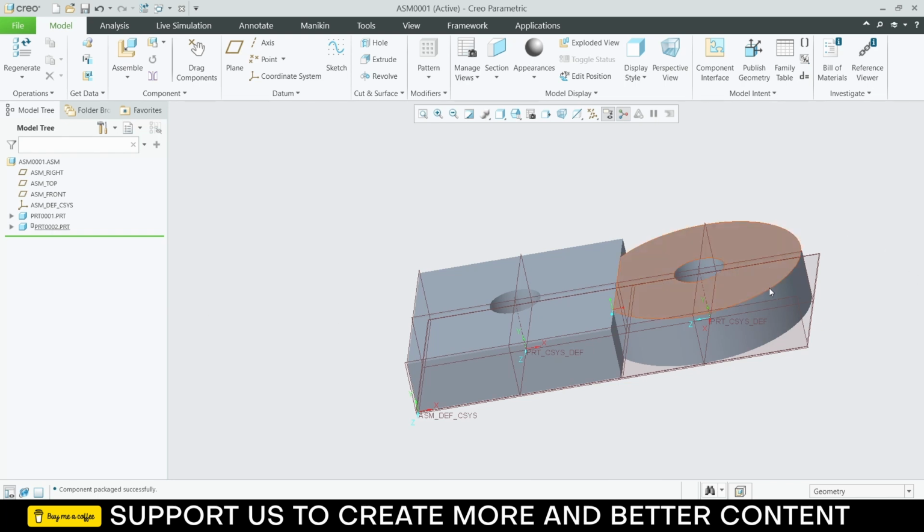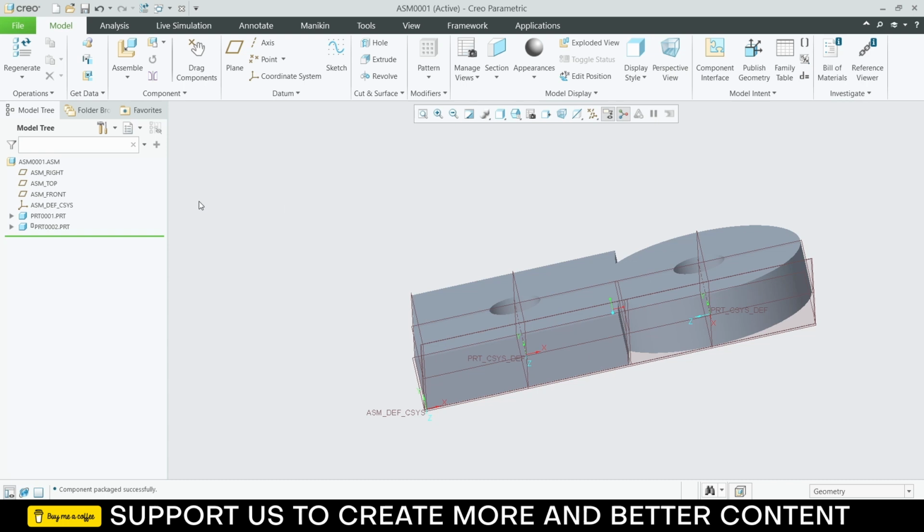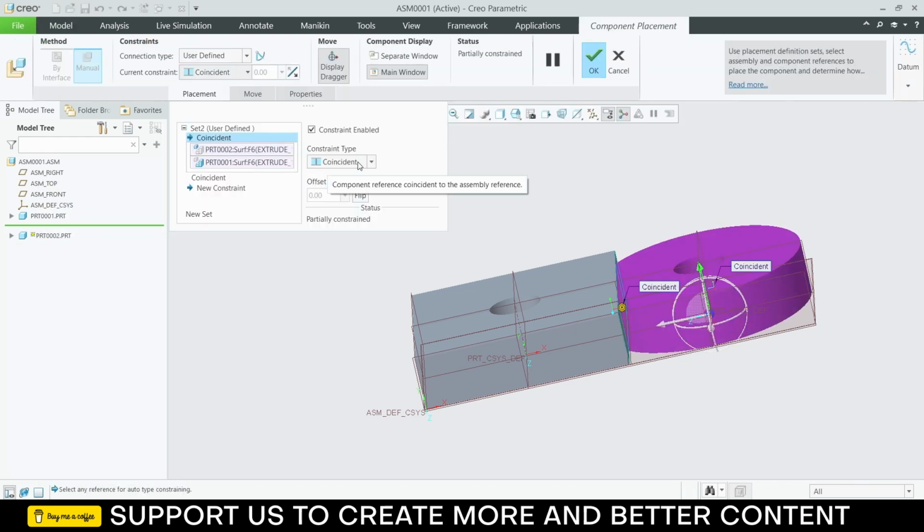Now, suppose for some reason you say, hey, I want to delete that constraint, the face mate. How can you do that? That is also a necessity. So right click on here. You can see the different kinds of mate constraints. Select this one, and notice it is the face one. Right click, remove. So now these faces are not attached to each other. Similarly, right click this one, remove.